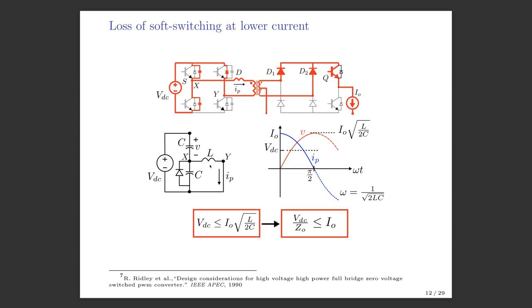And starting with some initial condition, right? And if you have studied a little bit of electrical engineering, you know an LC circuit like this will start oscillating sinusoidally. That means the current through this inductor and the voltage across this capacitor will start changing sinusoidally. And that is what will happen here. So you see this blue is the current through this inductor, which will start falling sinusoidally. And this red is the voltage across this capacitor, which will start increasing sinusoidally.